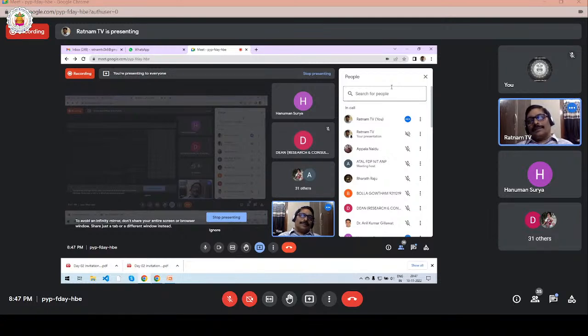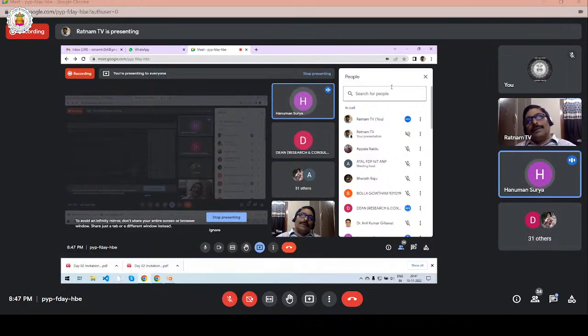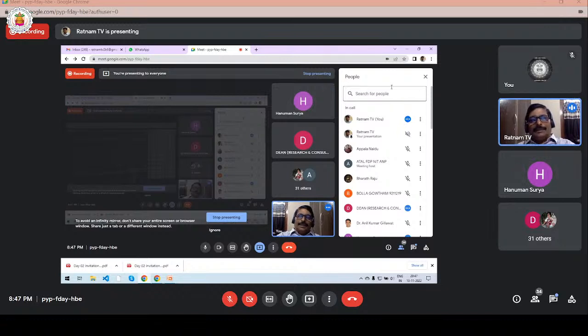Later, after that, have you used, sir, any type of filters, like digital filters? Yes, filters also can be used. Silencers are another way of reducing noise. Reactive silencers and baffled silencers also can be used. Whatever we are using in automobiles, reactive silencers are used. The noise path is directed in different ways, so there are different compartments in the silencer. The path is split into different compartments, and the noise emanating from the engine is reduced by splitting it into several noise components.